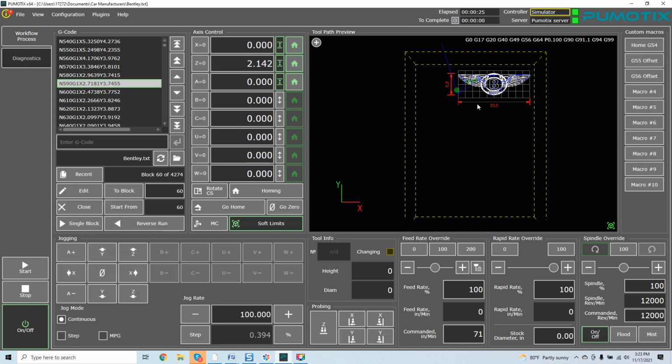You would naturally do your touch off at whatever location you are in your offset, make a mark on the table where that offset position is. I have guys that take a spoil board and actually engrave the offset position there, and you're ready to go, guys. I mean, this is how fast this is. And best of all, everything is saved.